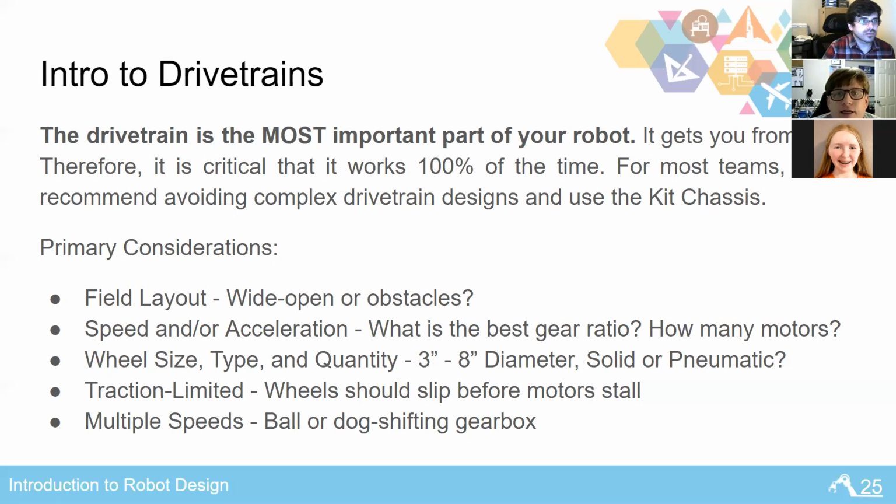And in that case, you want to make sure you have enough power going in the direction that you're going and not being divided out by vector summation. If we were to ever want to go sideways, I would look more at swerve style than mechanisms.